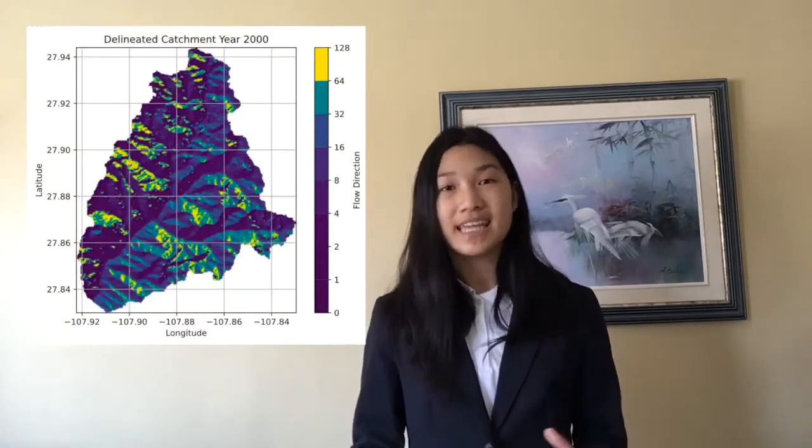Further data pre-processing was required for the ASTER satellite products, such as the correction of depressions and flats. Using the digital elevation model and a generated flow direction grid, the slopes from the topographic gradient were calculated to delineate the watershed. Following this, algorithms applying percolation theory were programmed and tested on the area of interest.